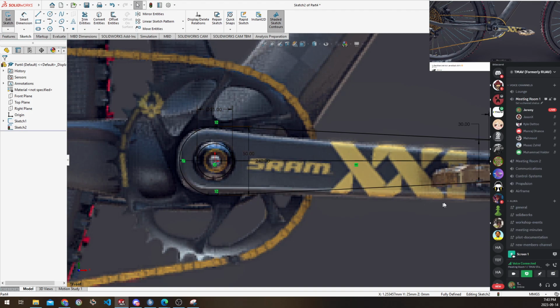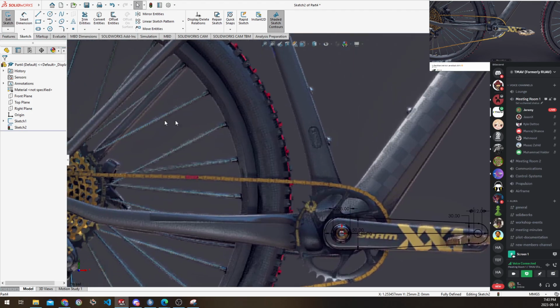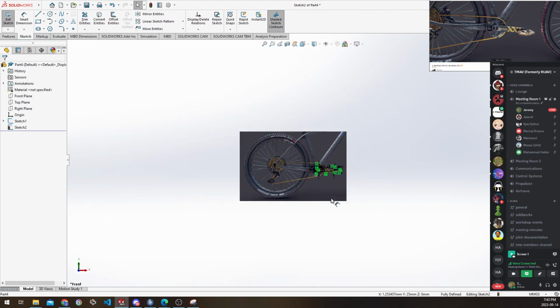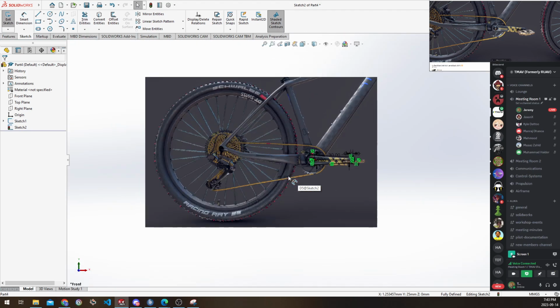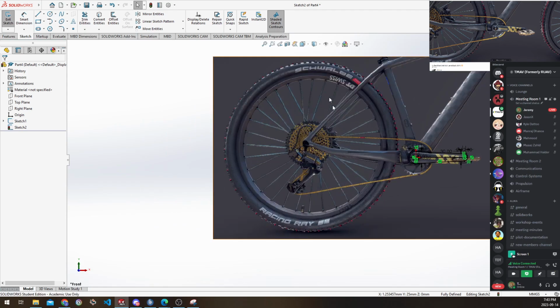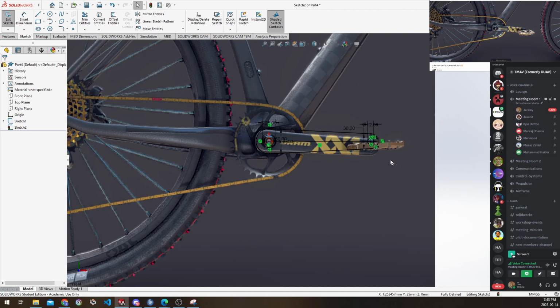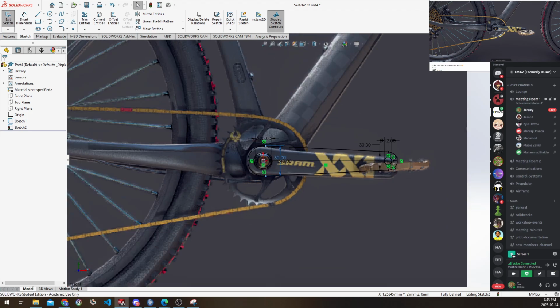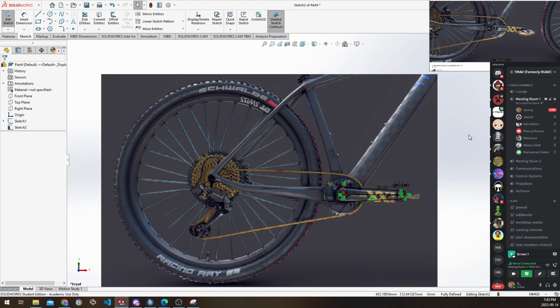You can see it's very close to the picture of the model. It's never going to be perfectly on because there's a lot of different errors we're seeing here. One, for example, is the perspective shift from this. We're looking through the center of this axle, which means the wheel is warped. So the reference dimension we put in is not technically correct. You know, even between the length of the shaft, there's going to be some distortions and stuff like that. So given all these things, this is a pretty good approximation of what we're looking at.